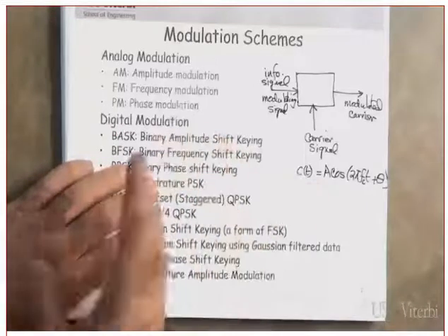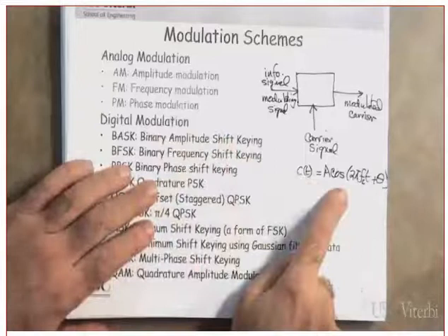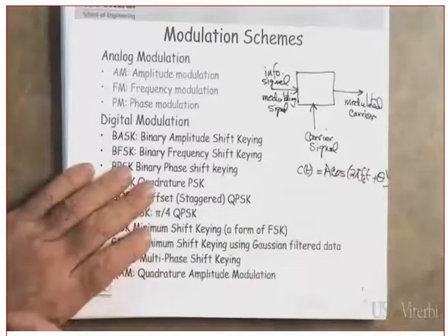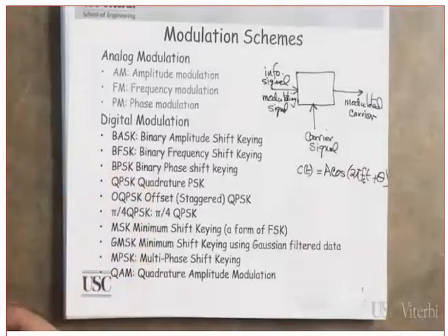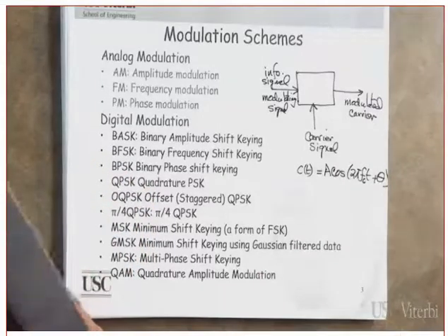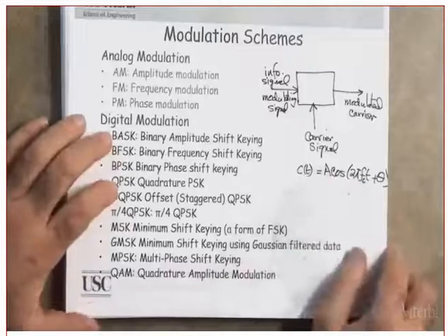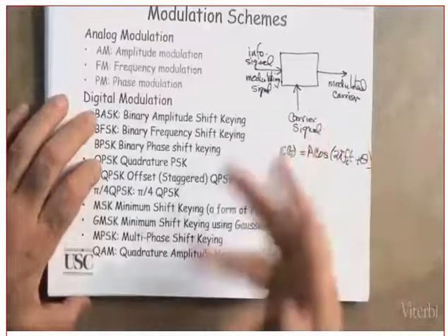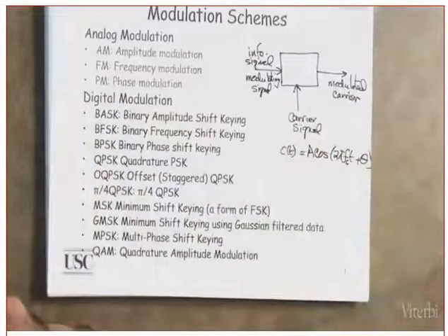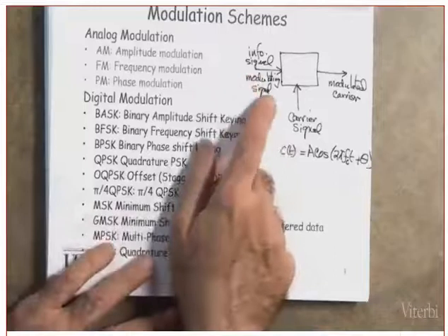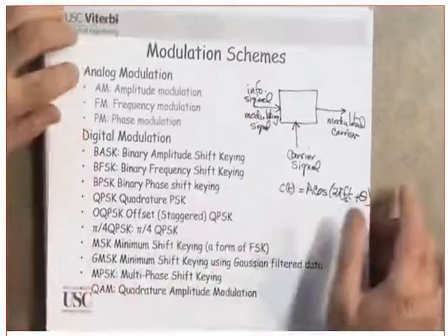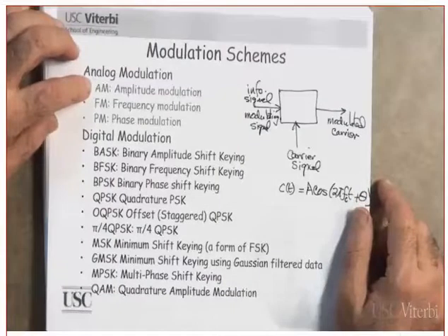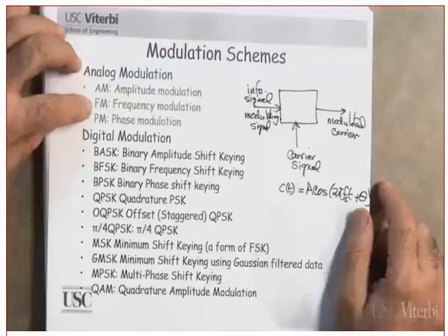Especially the frequency is a big question mark. Why? Because who is generating this? An oscillator. When we get to the oscillator, we will see that it is not going to be a pure, clean oscillator. Now, how many parameters does it have? Three parameters: the amplitude, frequency, and phase. Modulation is the process of altering or changing one or more of these parameters in accordance with the modulating signal. In analog modulation, we have the usual suspect, AM. AM stands for amplitude modulation. FM, which means what?